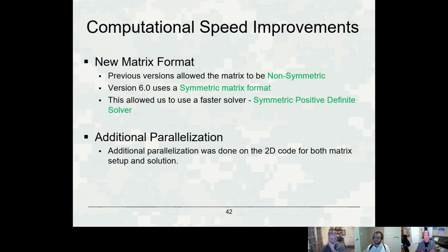Yeah, so you essentially have an equation built to solve full momentum over a face, right? Yep. In a 2D area, and you can have thousands, tens of thousands, 100,000, millions of faces. Each one of them gets an equation, right? Right. Or actually two equations, because you're also doing conservation of mass. Right. And then you're doing it in 2 dimensions. And in 2 dimensions, right.